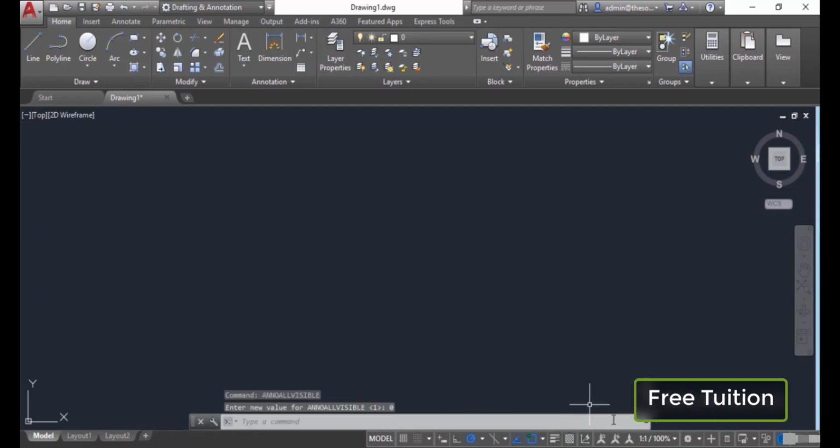So you can just deactivate all the remaining options, but make sure only these three options are on, because these are the settings that we will use for the remaining drawings. Now since we have already set our limits and units, we'll save that as well as this status bar setting as a template. To save it as a template, go to this application button